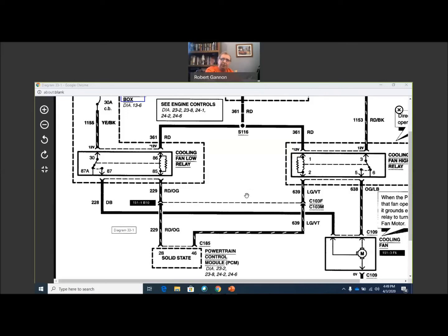When it comes to relays, usually any circuit that has a relay, the place to do your diagnosis is right from the plug where that relay goes in. And the reason for that is the entire circuit comes together in this one spot right here. So you can test all four branches. You can test power here, you can test power here, you can test this, you can test the ground, you can do it all in one spot. You don't have to move your feet. Very convenient.